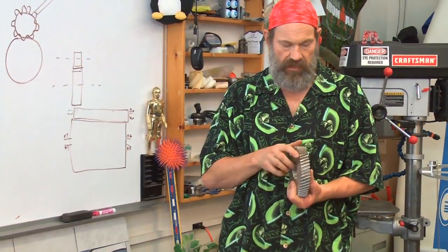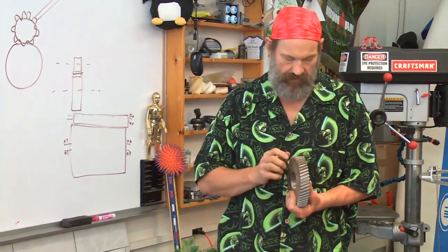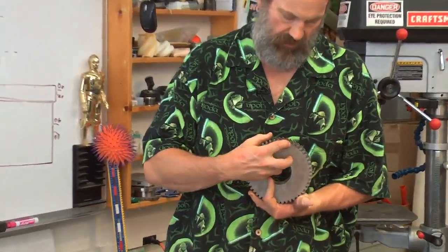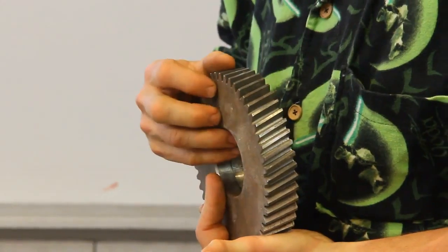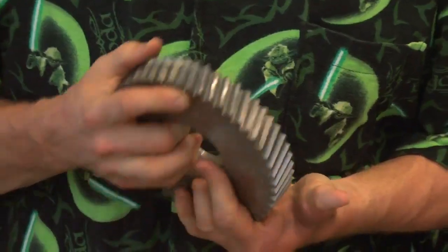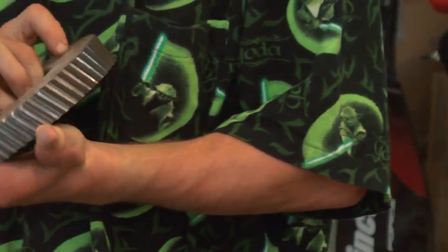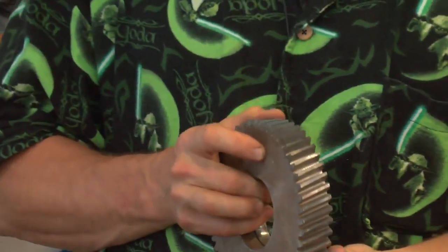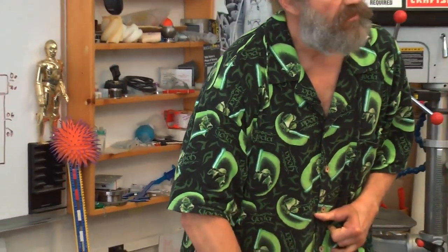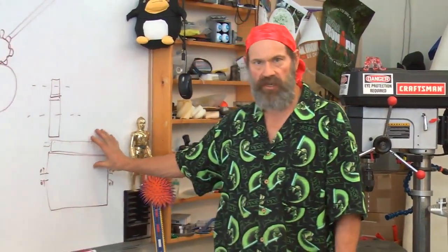Well, first of all, helical teeth are a little more tolerant. But look at this set of helical gears. Look at the thickness of the tooth and the width of the tooth. That's about 5 to 1. This is where we get back to St. Venant's principle. You can push it sometimes to 10 to 1, but as you go much more beyond that, you start having other problems associated with the gears.